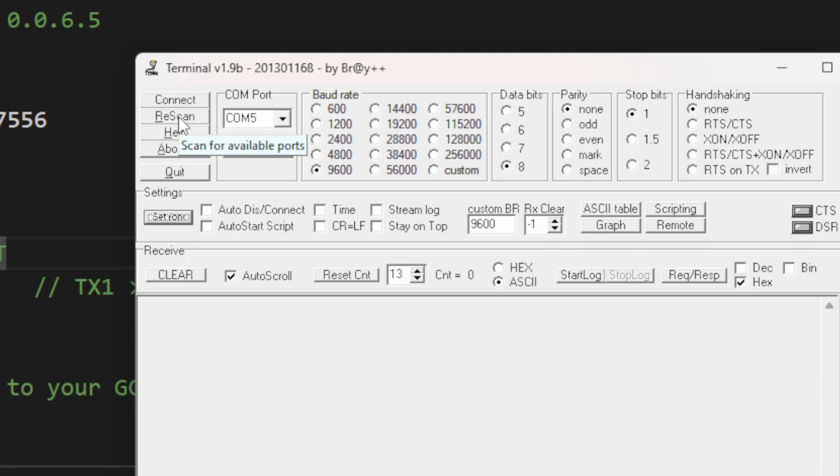I'm going to scan or rescan my computer, and I've got two communications ports set up, COM1, COM5. If I unplug that USB TTL converter and I rescan, I have 1. If I pop it back in and I rescan, I will see COM5. That tells me that's COM5. Now, it's been programmed and it's running, therefore we're going to get some instant results.